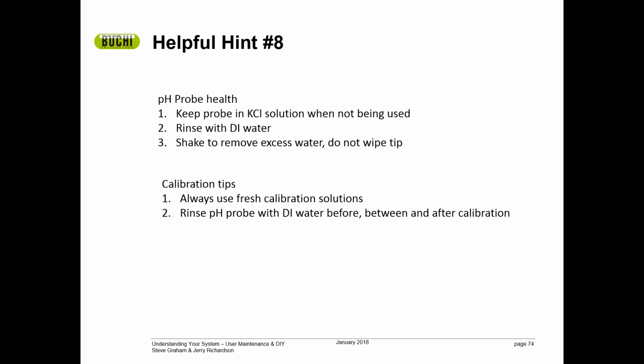Calibration of the pH probe should be done on a daily basis. We suggest that in our manual. You may have even a more frequent SOP in your laboratory, but it should be done on a daily basis. It only takes a few seconds, very simple.